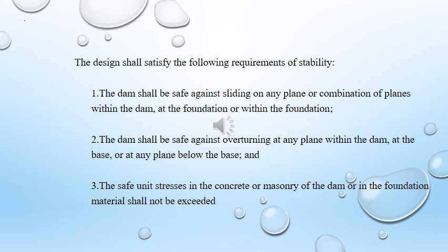The dam shall be safe against overturning at any plane within the dam, at the base or at any plane below the base. And the unit stress in the concrete or masonry of the dam or in the foundation material shall not exceed the permissible value. So, now these are some stability criteria.